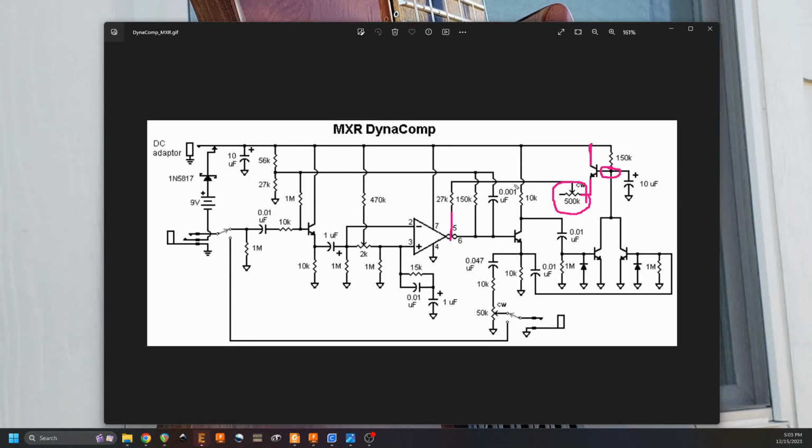This potentiometer is going to control the sensitivity, because it's going to govern how much of our voltage becomes current. Because we have a fixed voltage here, and we can change this resistance, then using Ohm's law, as we change our resistance here, we're changing how much current flows into this pin. Okay? So we have a small fixed resistance here, so that even if this thing is completely dimed, we still have some amount of resistance, so that we have some amount of current going through it. But it's small compared to this, so the pot dominates the control of how much current there is.